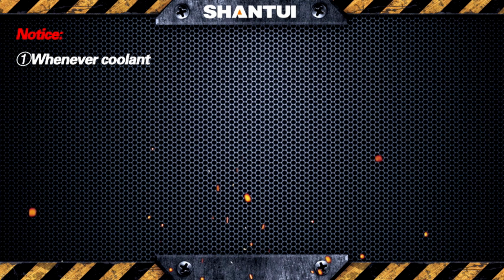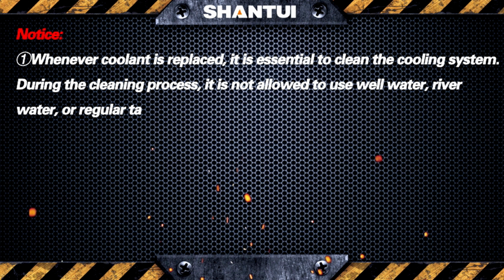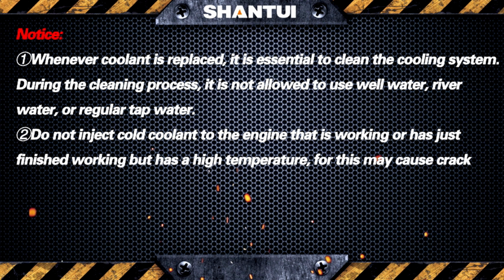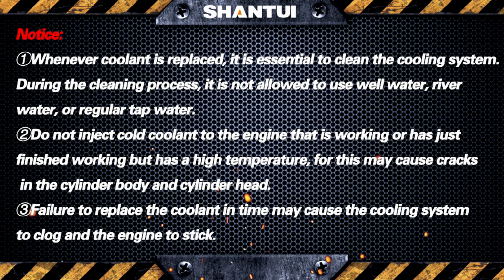Notice: 1. Whenever coolant is replaced, it is essential to clean the cooling system. During the cleaning process, it is not allowed to use well water, river water, or regular tap water. 2. Do not inject cold coolant to the engine that is working or has just finished working but has a high temperature, for this may cause cracks in the cylinder body and cylinder head. 3. Failure to replace the coolant in time may cause the cooling system to clog and the engine to stick.